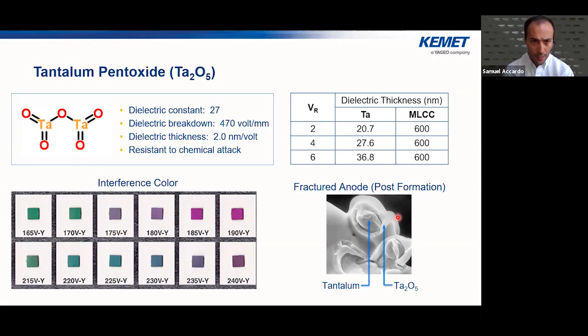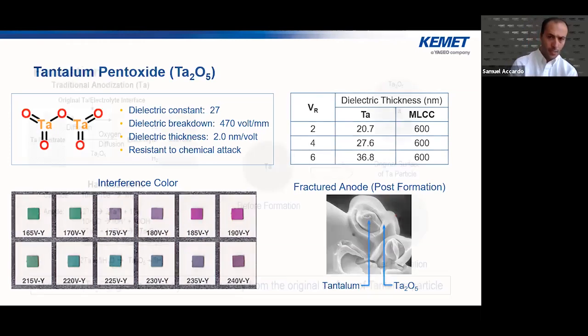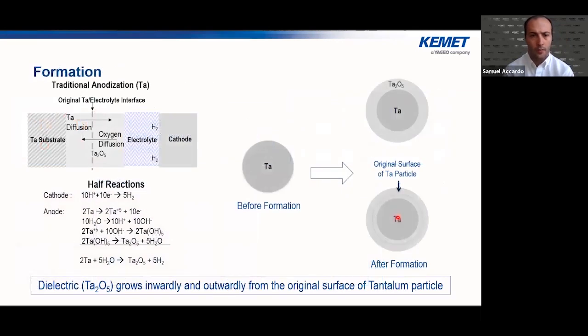So the tantalum pentaoxide is a very robust dielectric, and it's capable of handling higher voltages per thickness. It's a very good dielectric for that. Now, looking at the formation of the tantalum pentaoxide, essentially we have tantalum pellets that have been compressed and sintered on a tantalum wire.